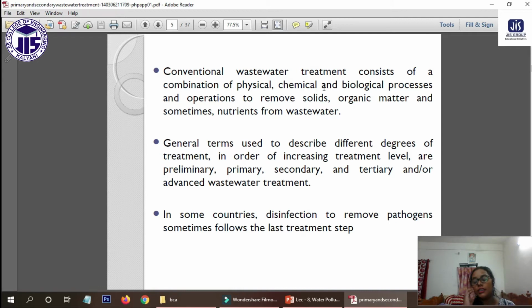And the tertiary treatment is the last step. For tertiary treatment we use activated charcoal, which can absorb so many things. All the remaining particles can be absorbed by the activated charcoal, and then it can refine the water. So this is the last step, the tertiary treatment. Now one by one we will see the steps that we will follow.